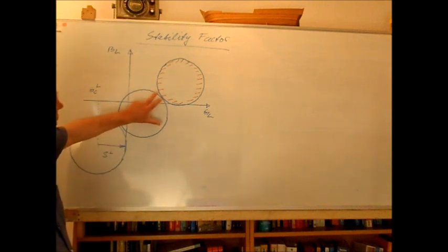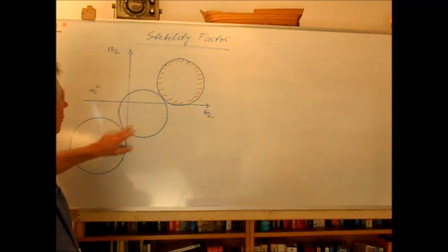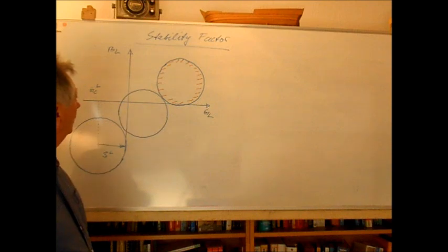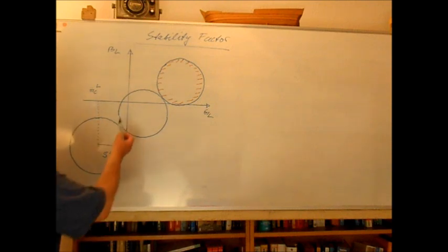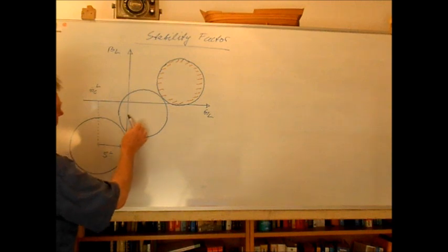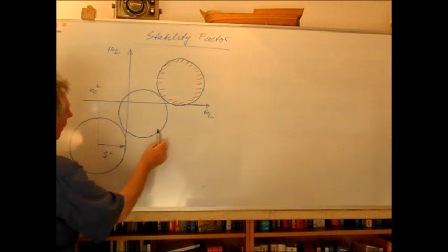Of course, if I connect any of the load admittances inside, they will result in a negative input admittance, but only this part of the circle lies in the right half plane.